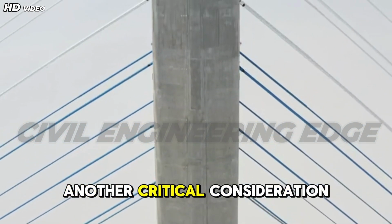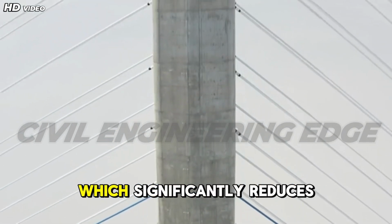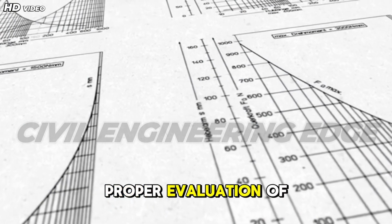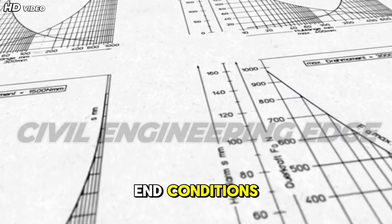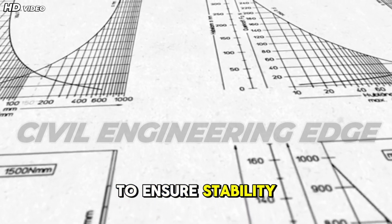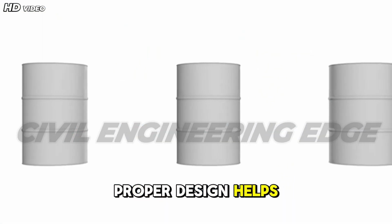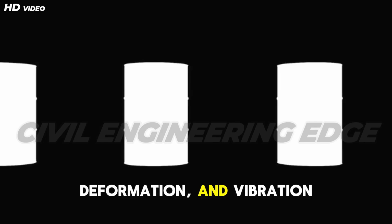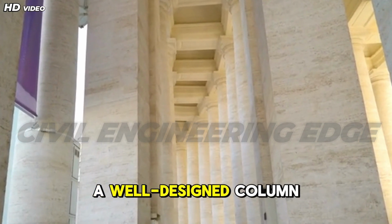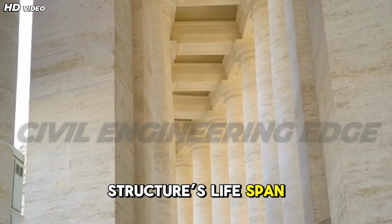Slenderness effects are another critical consideration. Long columns are prone to buckling, which significantly reduces their load-carrying capacity. Proper evaluation of effective length, end conditions, and slenderness ratios is necessary to ensure stability. Serviceability is equally important. Proper design helps control cracking, deformation, and vibration, ensuring comfort and durability. A well-designed column minimizes maintenance issues and extends the structure's lifespan.